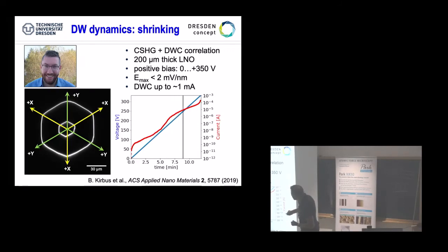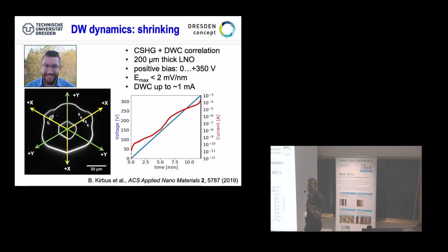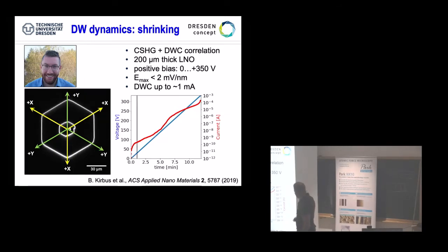You see how the domain wall really goes in, rather than stopping. So this was an XY picture. On the other side, you see the reddish curve, this is the current now. It goes up, and after having pulled the system and then going back to 10 volts, bang, the current is up here, 10 to the minus 4, 10 to the minus 3 amps. So huge currents are flowing along one single domain wall. That's the domain wall that you see here.